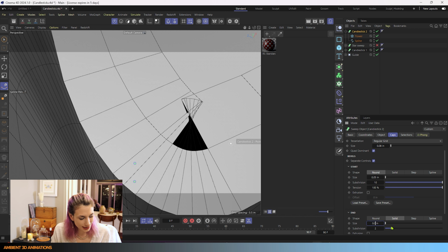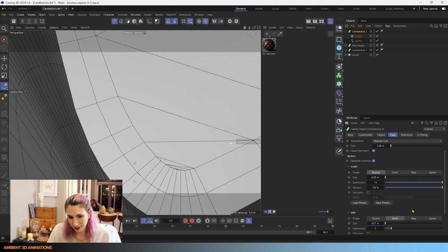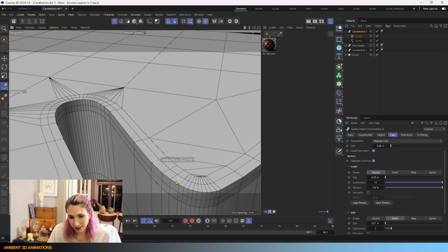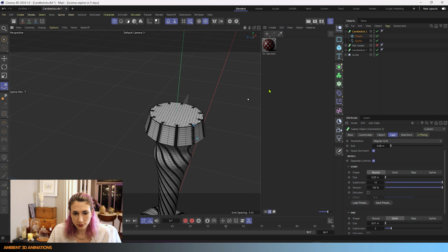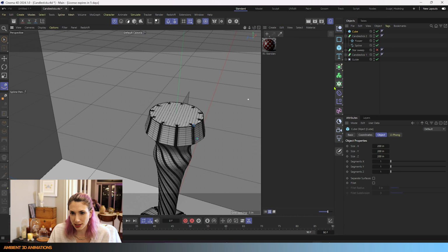So you run into issues with bevels if you create a size of bevel that is larger than the surface area that is available to create that bevel. So the radius is important, the size of that radius is important. In this case, you'll notice this actually isn't rounding like what it was before. And the reason why is because solid is actually a type of bevel that works when you use subdivision surface. So just briefly, I'm going to show you what the subdivision surface is.